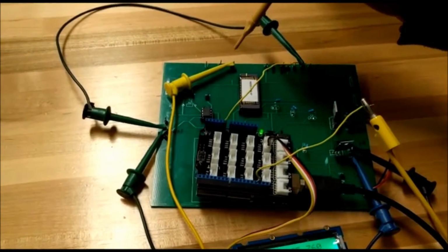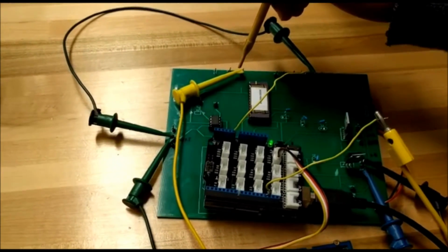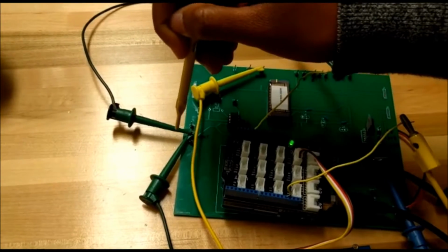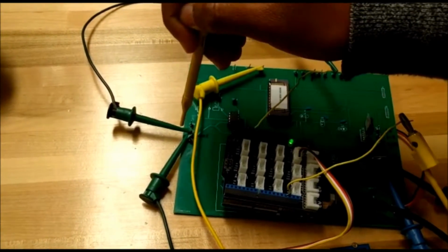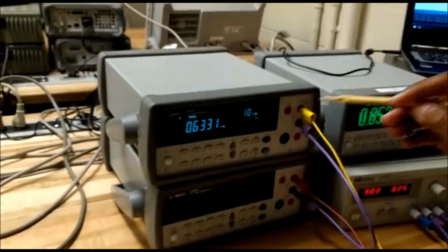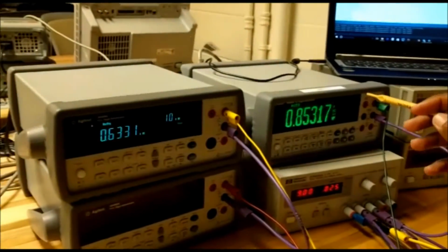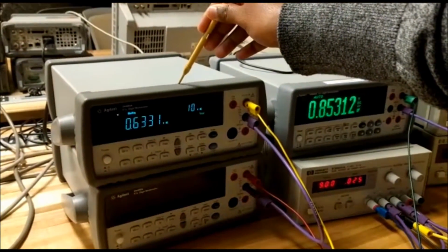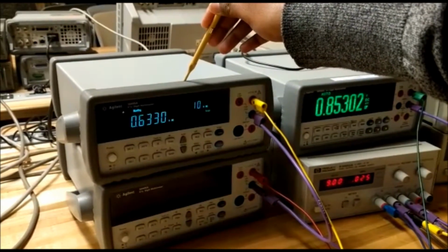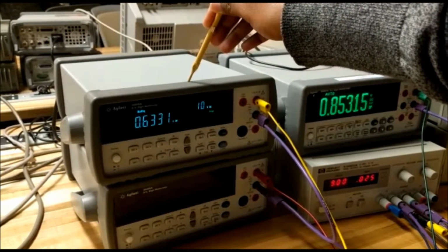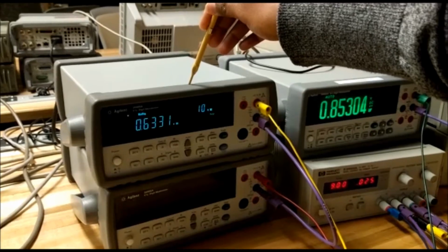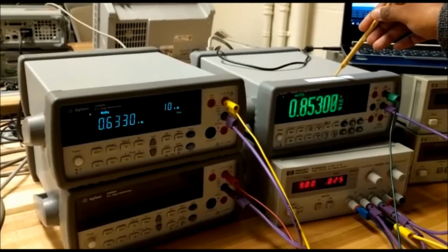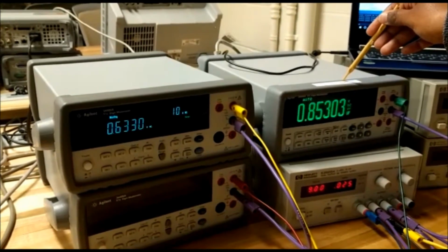We are measuring two outputs from our chip. One is the bandgap reference output and the other one is the PTAT output, which gives us a temperature and voltage correlation. You can see that we are measuring both the outputs at room temperature over here. This is the bandgap reference output. That means our chip is going to produce a constant 0.63 volts throughout a temperature range of minus 20 to 50 degrees Celsius, and this is the PTAT output voltage at room temperature.